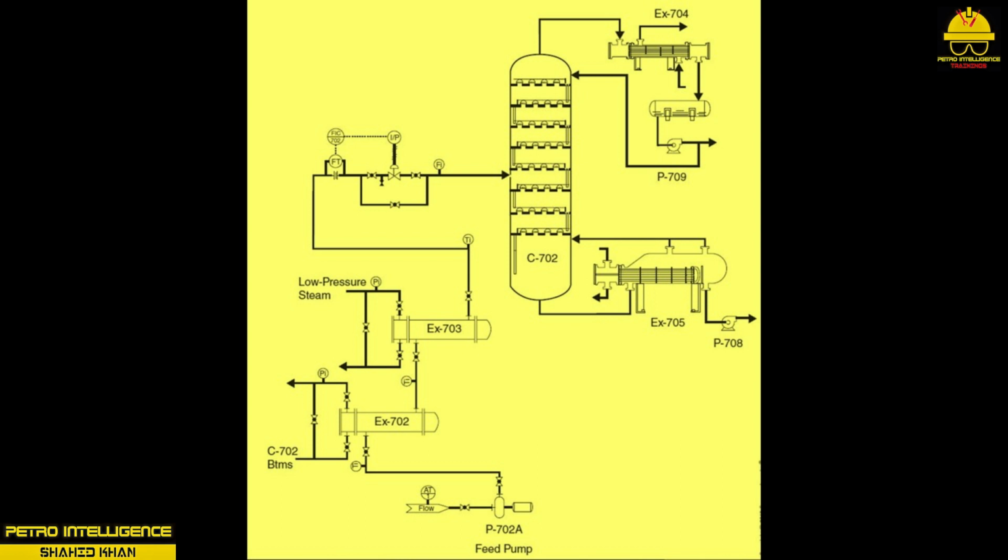Steam flow is open to the tube side of the kettle reboiler X705. As the temperature starts to increase, the flow rate is increased in 50 GPM increments up to 200 GPM on FIC 702.